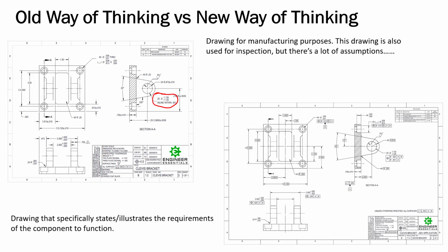But look at the location of them. Look at the tolerance on this one: 3.5 thousandths plus or minus, coming from the bottom of the part, which we did say the bottom of the part is important. Over here, it's primary datum. But now look, we're coming off this bottom rail down here, and we have plus or minus 3.5 thousandths from the bottom up. That does not relate to function whatsoever.